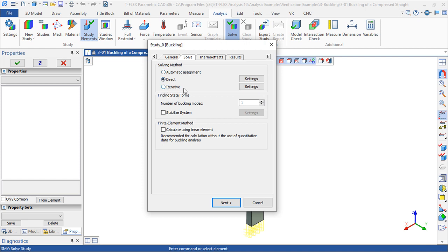In this direct one, the system of equations is solved by Gauss method, which takes a lot of RAM compared with the other one with the iterative method. But the direct method is better for small problems, and when we are in presence of less than 100,000 degrees of freedom. This is a balance between complexity and time to calculate things.